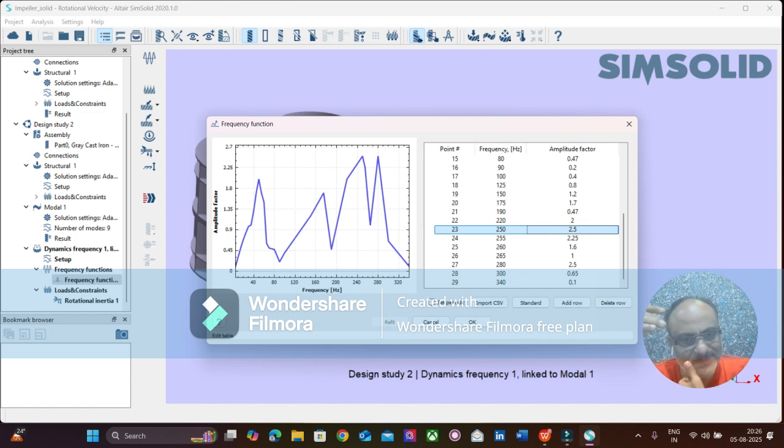So on one end you ping it with a tuning fork, and on the other end there is going to be a damping system. That damping system can be a viscous damper, like some kind of cushioning, neoprene cushioning, or maybe some damping materials, some fabrics. So here we are taking care of the damping with an external fabric or material.